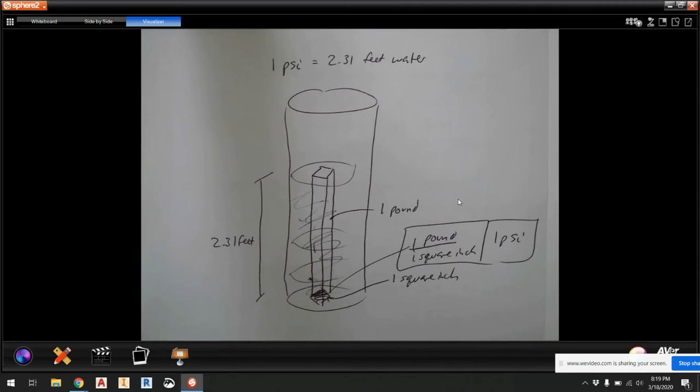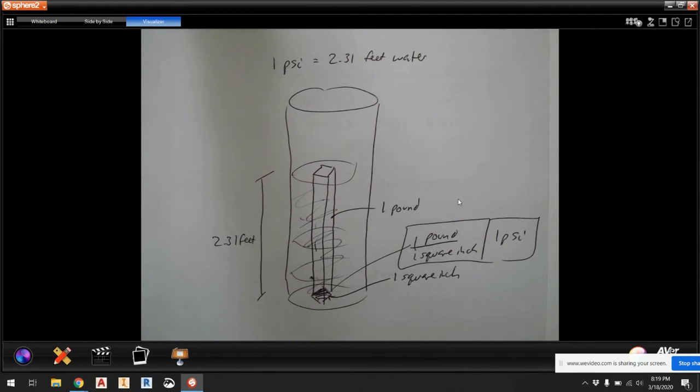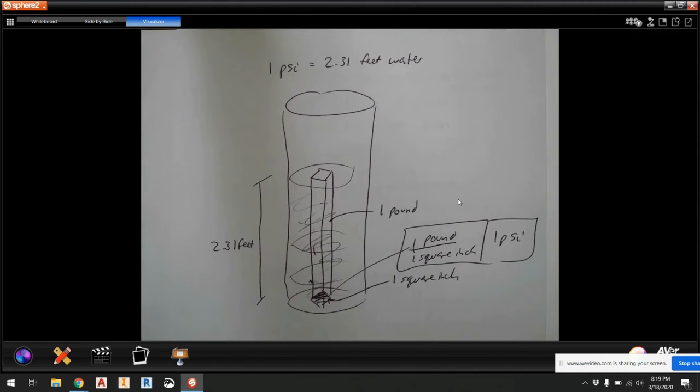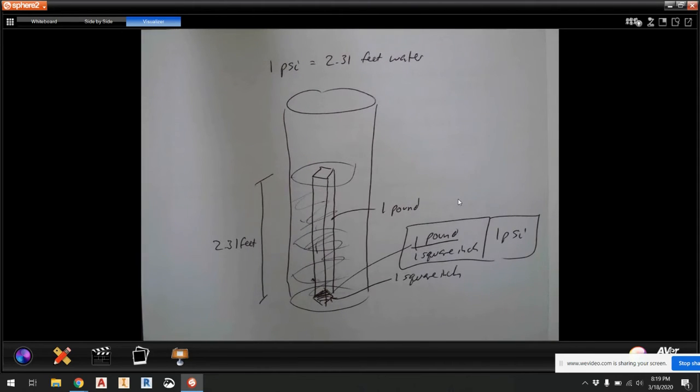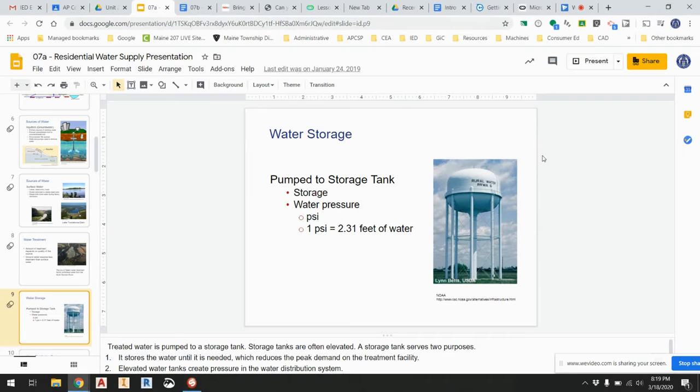All right. So when we're talking about water pressure, a lot of times, this is a very old method of analyzing water systems. It's a very old thing to do, and so a lot of times we're going to talk about pressure as something you're going to see very soon here: head. They talk about the head, which really will relate to pressure. But head is measured in feet, whereas pressure is measured in pounds per square inch. So we're going to need to be able to convert between the two.